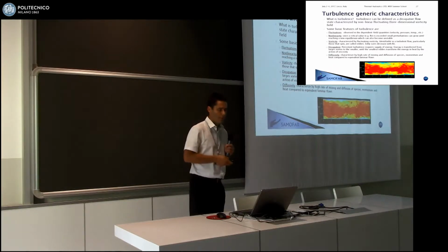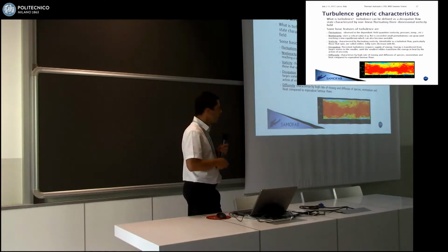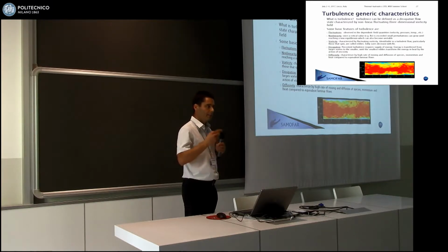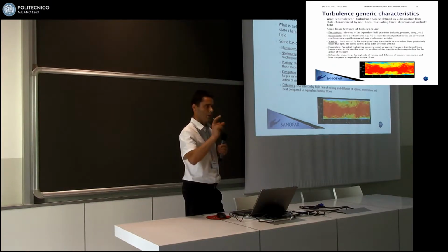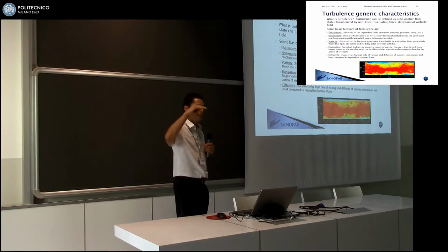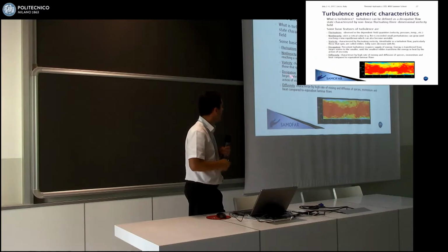Turbulence is not so simple to define. You can say that it's a dissipative flow that has nonlinear fluctuations and has three-dimensional vorticity. Vorticity is a very specific term. It means a rotation of the fluid around some point. If you want to characterize turbulence, you will probably mention all these five features, okay? Like you have fluctuation of the properties that is very nonlinear. So the flow was laminar, and then when you increase a little bit the velocity, then it becomes turbulent. This was happening at a threshold velocity.